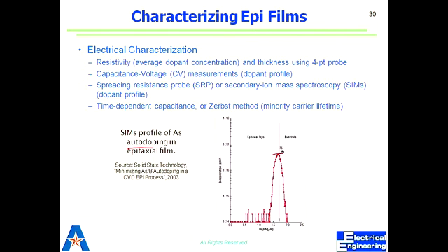Yeah, this is what it is, and then you can measure from that resistivity. You can measure the concentration. So that tells you about the out diffusion, if the diffusion has gone deeper than what you wanted.